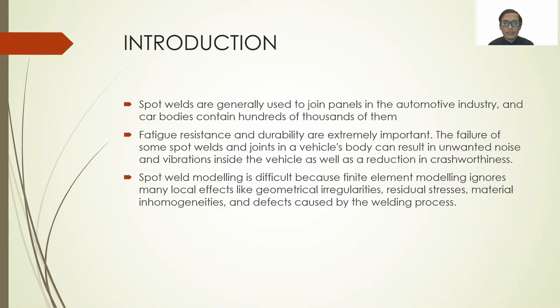Spot weld modeling is difficult because finite element modeling ignores many local effects like geometrical irregularities, residual stresses, material inhomogeneity, and defects caused by the welding process.